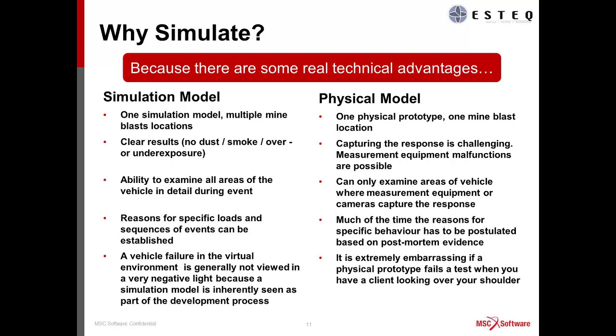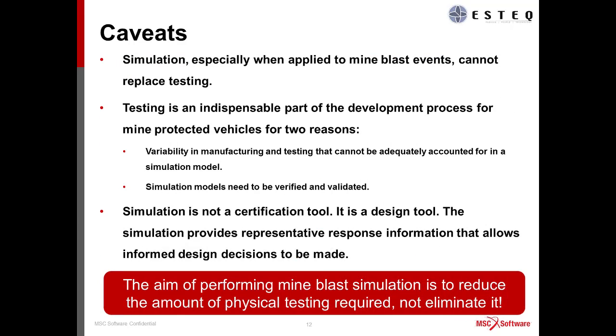All right. I need to mention a few caveats before I continue. I've painted a very rosy picture for simulation, but there are a number of things to keep in mind. Simulation will never replace testing. This is especially the case when you're performing mine blast analysis. The reasons for this are twofold. Basically, there's a lot of variability in the manufacturing and testing that cannot be adequately accounted for in the simulation model. And secondly, simulation models need to be verified and validated. There's just no escaping that fact.